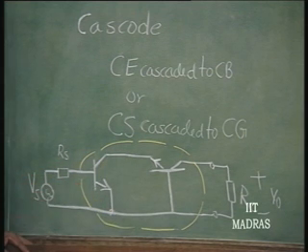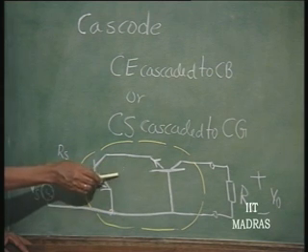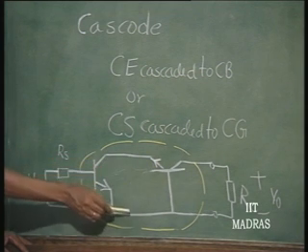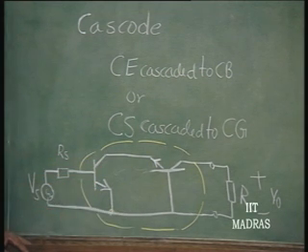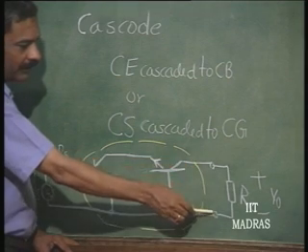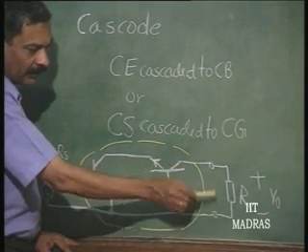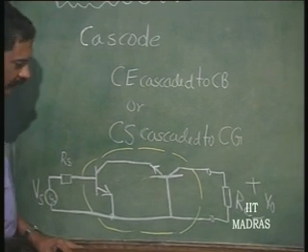The intermediate time constant is caused by the output resistance and input resistance in parallel and then the capacitance at this junction. And this time constant is caused by the load, the output capacitor and the output resistance of the structure.